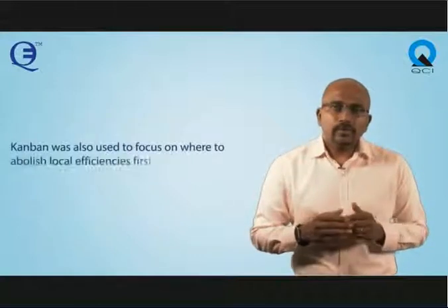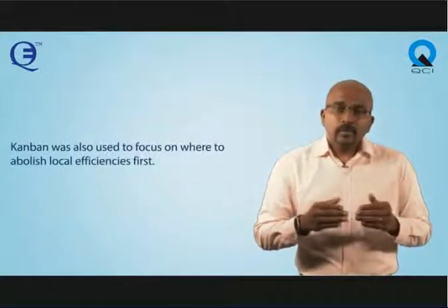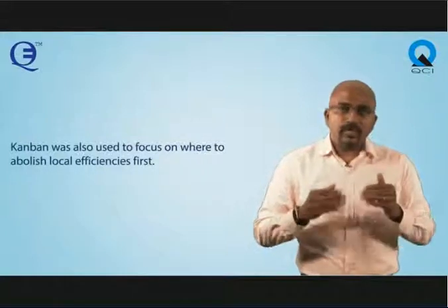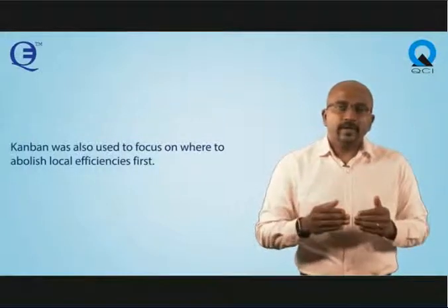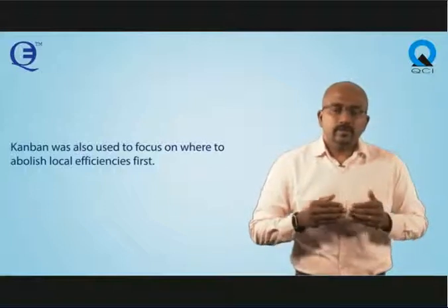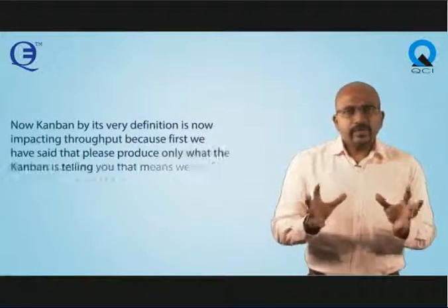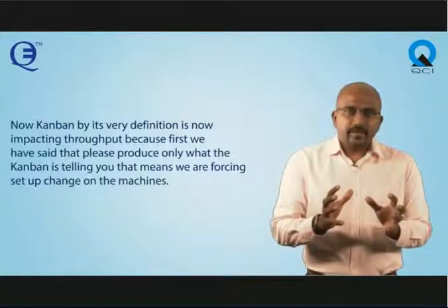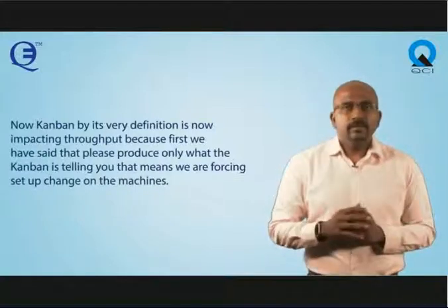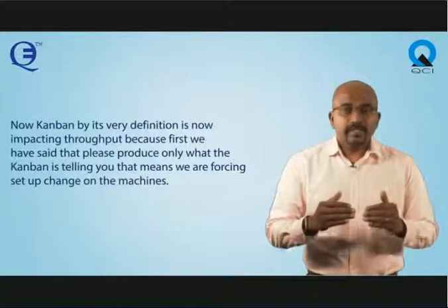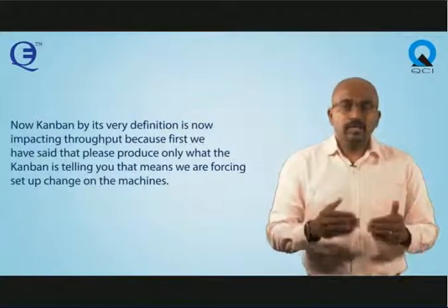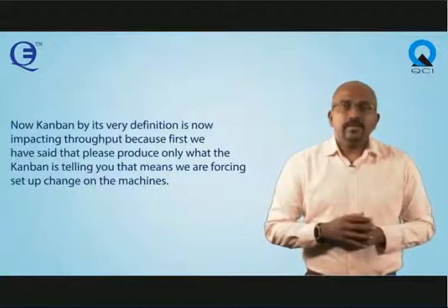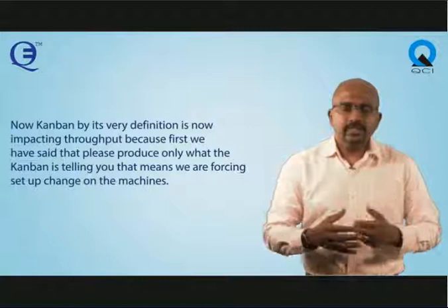Kanban was also used to focus on where to abolish local efficiencies first. Now Kanban by its very definition is impacting throughput, because first we have said that please produce only what the Kanban is telling you. That means we are forcing setup change on the machines. If the card has come, you have to produce it.